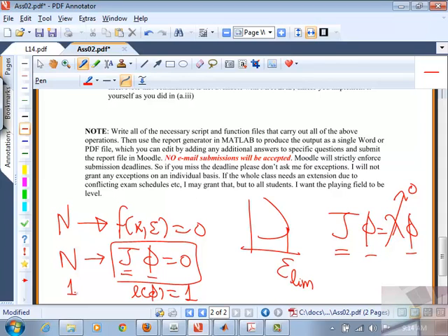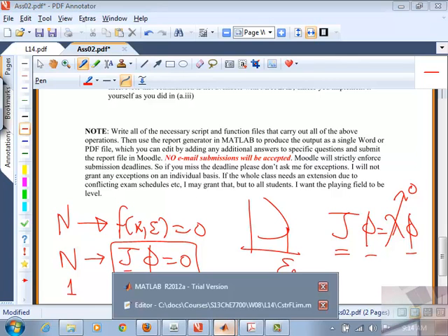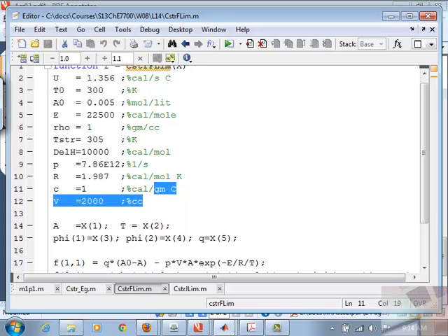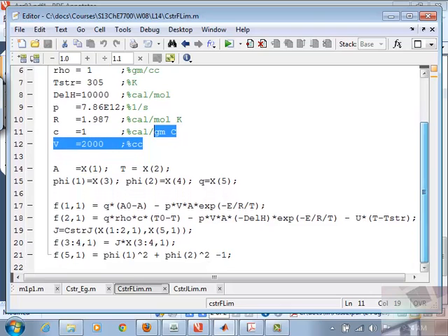And we have seen what it is specifically for that reactor problem with 2 equations. So we ended up with 5 equations, and those 5 equations are the ones that you see in this function. There is no substitute for going and thinking about each line and making sure that you understand it. The first line, 17, is the first equation for the CSTR. 18 is the energy balance equation for the CSTR. 19 is where we are calculating the Jacobian of the 2 by 2 system. And 20 is where we are adding the third and the fourth equation of the extended system, which is nothing but the Jacobian multiplied by the null eigenvector, the eigenvector corresponding to the 0 eigenvalue. Those are stored in locations 3 and 4.